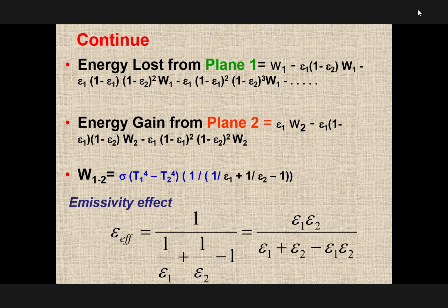And gray means they have a certain emissivity. You can take this effectiveness into consideration, okay? Therefore now we are able to calculate how much energy is emitted from one surface, the Stefan-Boltzmann equation, and if you have two surfaces that see each other all the time, we can calculate it if they are not black.